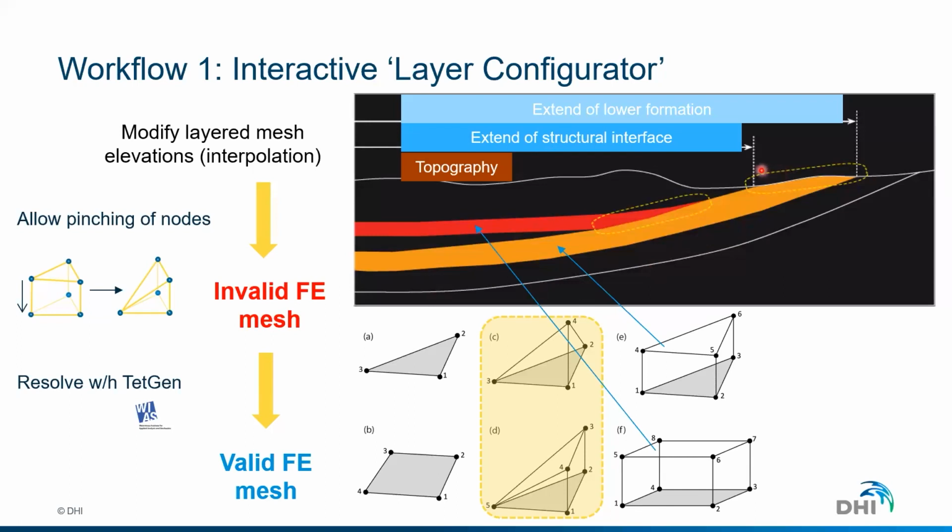The nice thing about the layer configurator is that you have the possibility to create rules according to the classes. We have two classes, fixable and movable, and with these two classes, you are able to build many complex models. The classes indicate if it's fixed, and if an interpolated surface is in contact with or touching any fixed surface, then FEFLOW knows where to stop this layer. And you can use this method to construct complex geometries.